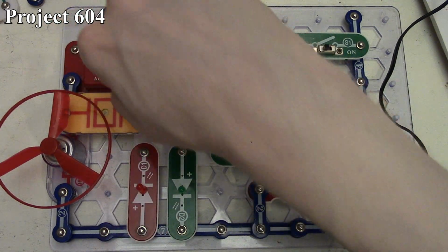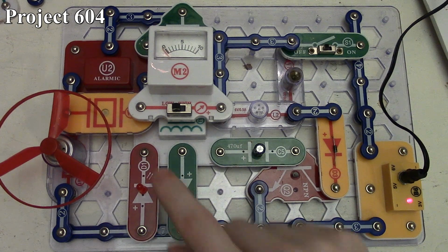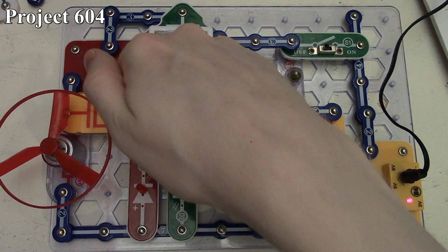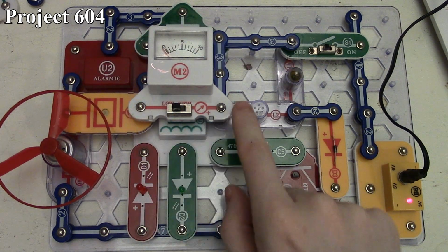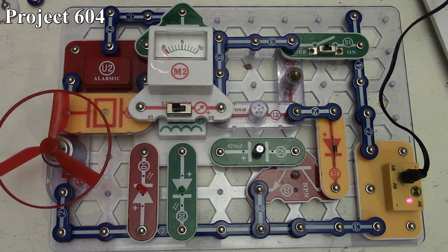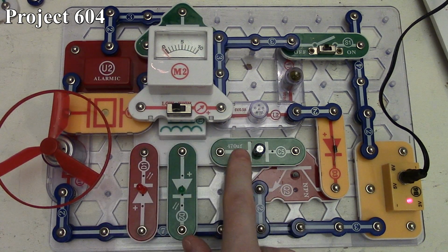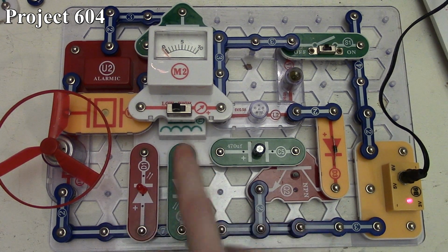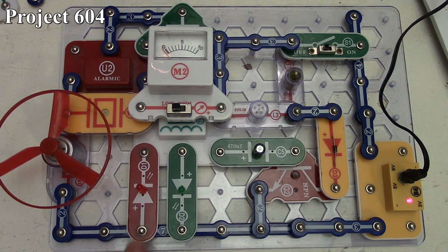And then the output of our alarm IC is doing a couple of things as well. Number one, it's putting output to our whistle chip here. It also connects across our meter, so we'll see our meter deflect a little bit as it's pulsing on and off. It also drives our transformer here, and the transformer has a couple of bits going on as well. Number one, it's got both the red and green LEDs in separate directions, so we'll see those pulse on and off with the output of the transformer there.